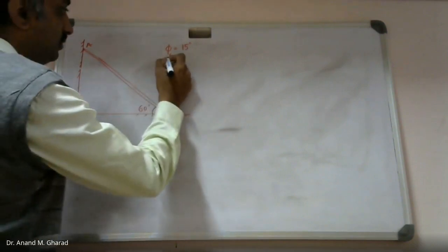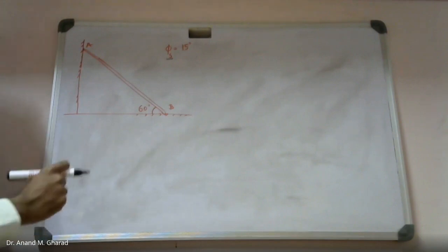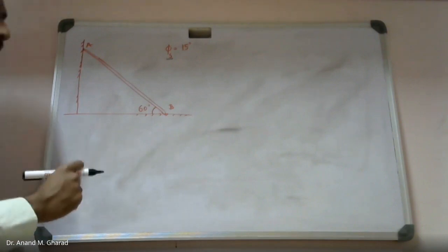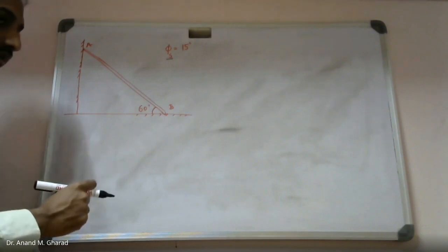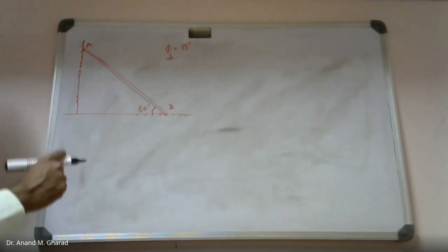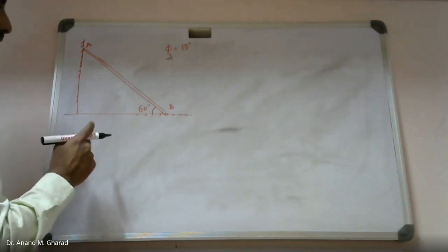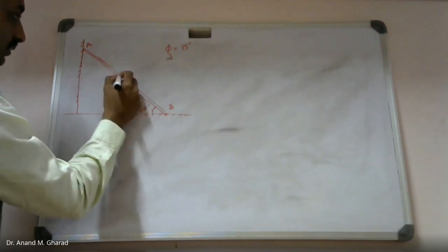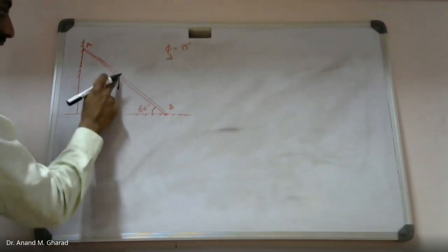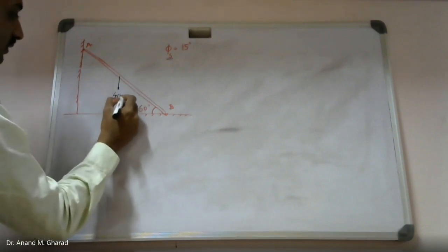That's why we have introduced this static term, because we know that this is not in ultimate motion. It has just started its motion. Okay, it has just impended. Now, once we know the complete situation, we can introduce the self weight. Self weight will be acting exactly at the center of this ladder. It is given as 40 Newton.